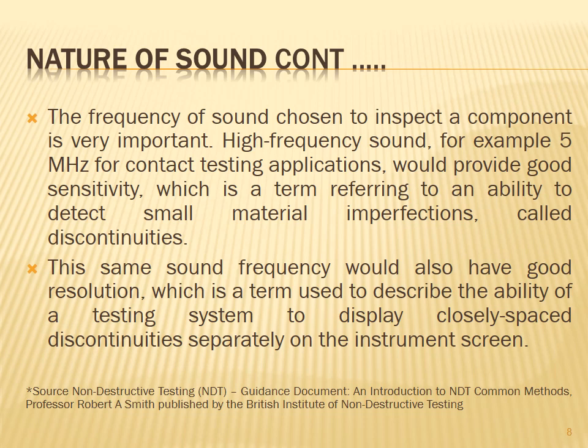High frequency sound, for example 5 MHz for contact testing applications, would provide good sensitivity, which is a term referring to the ability to detect small material imperfections called discontinuities.